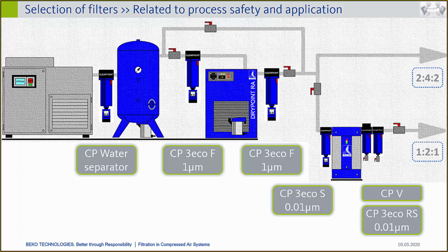But of course, any bigger size of filter is a higher price, not only for the filter housing, but also for the filter element. So finally, it's a complex calculation for the overall running costs. We will also come to that point on some of the next slides, and I would not recommend putting in bigger sizes just to reduce the pressure drop, because I think the disadvantages weigh more.